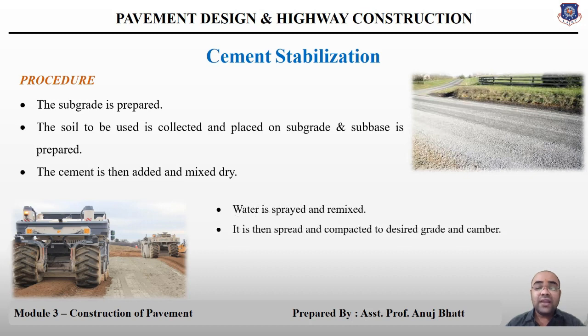Now it is then sprayed and compacted to the desired grade and camber. The surface is then cured by preventing the moisture from escaping, by covering with paper or by moist soil, as is convenient for that particular site. So this is how we perform cement stabilization.